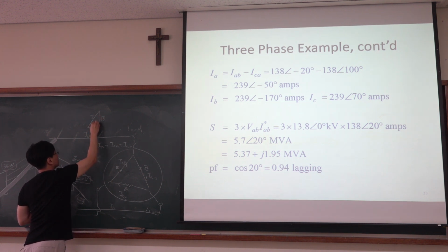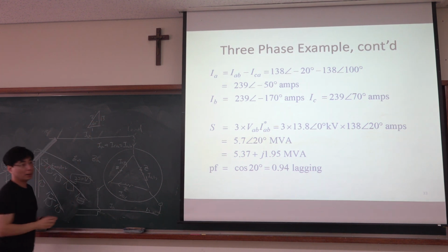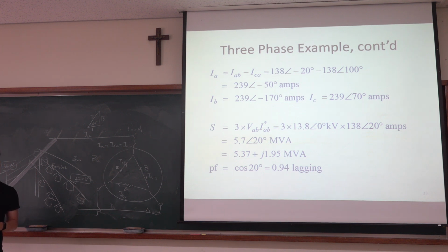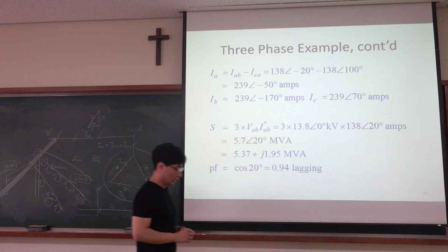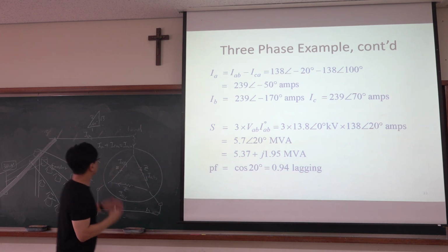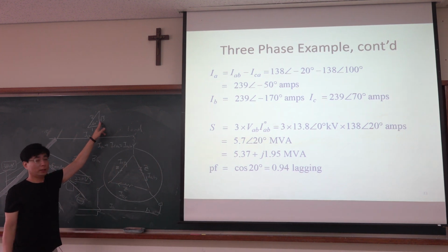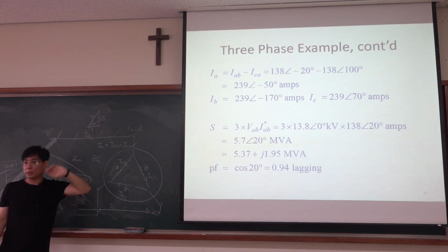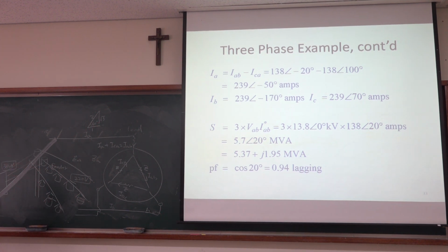Then this is a 60 degree angle. So the power factor is 0.5, and it happens in real situations. The angle is 60 degrees, so a very, very inefficient case. In that case, we can put reactive power at the load side using STATCOM or SVC.